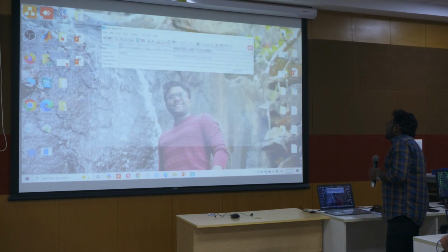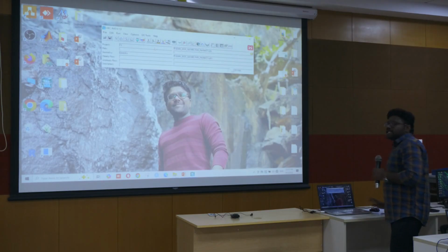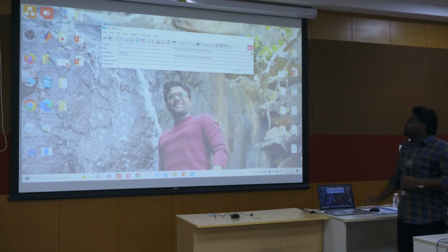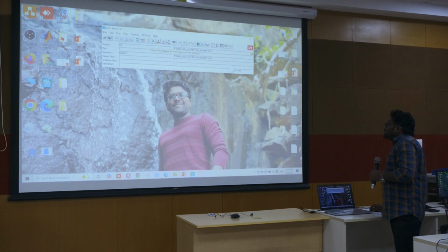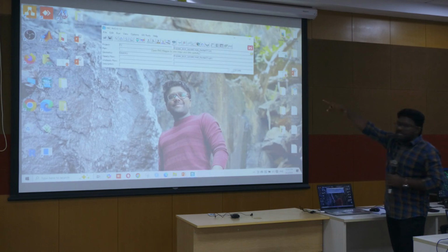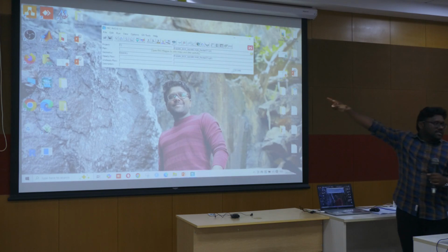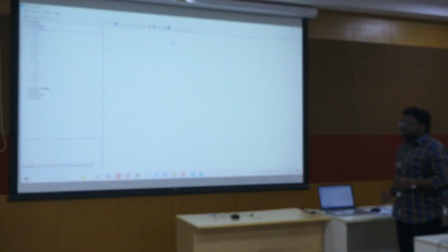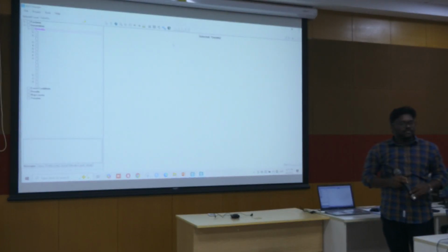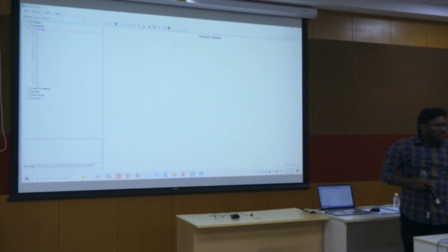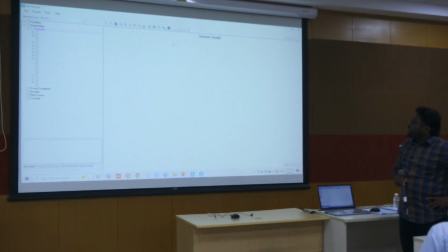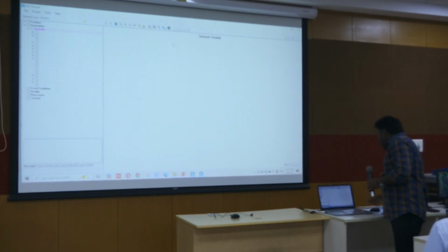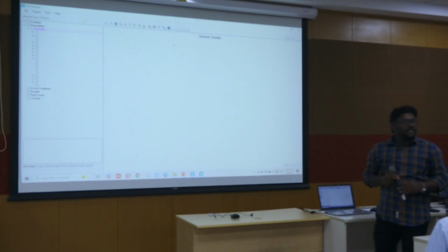So we are drawing the geometry using RAS Mapper. This layer option is Open RAS Mapper. Just click on that. Right?